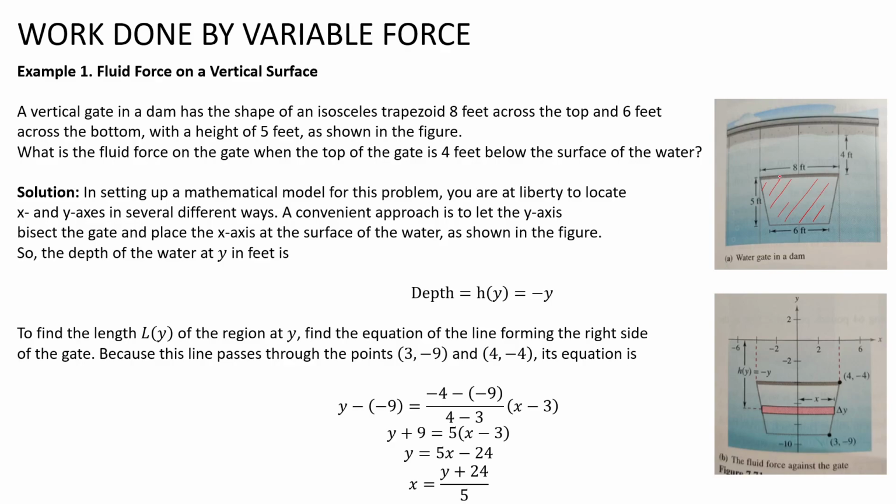After drawing your trapezoid, you'll be establishing your x and y plane in the diagram. My suggestion is to always make your x and y origin at the surface of the water. So the x-axis is the surface of the water, and the y-axis is splitting the polygon in its symmetrical axis, meaning it is dividing it into two equal portions.